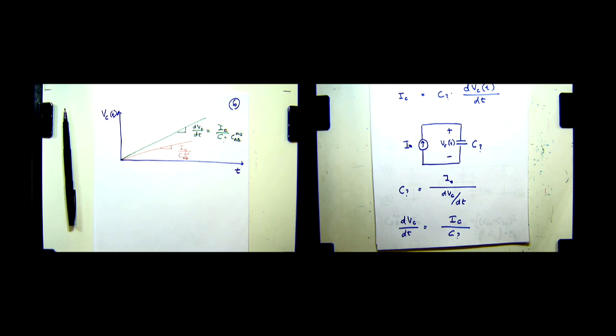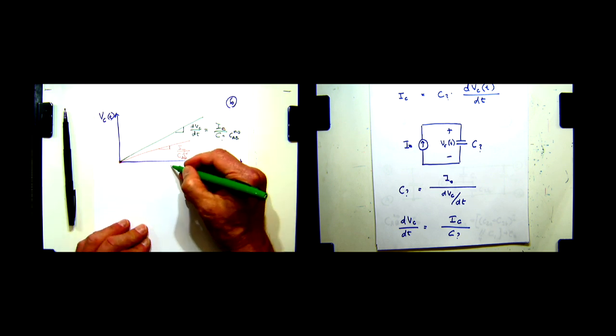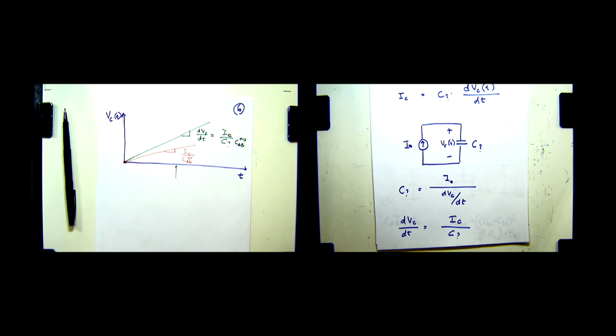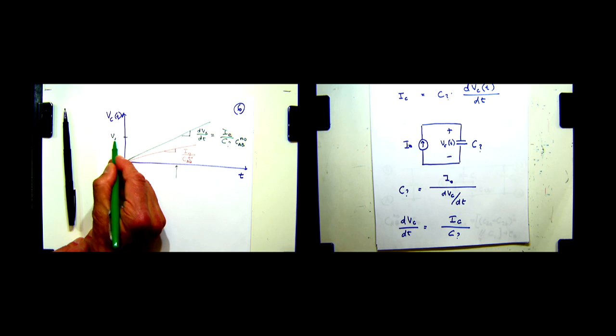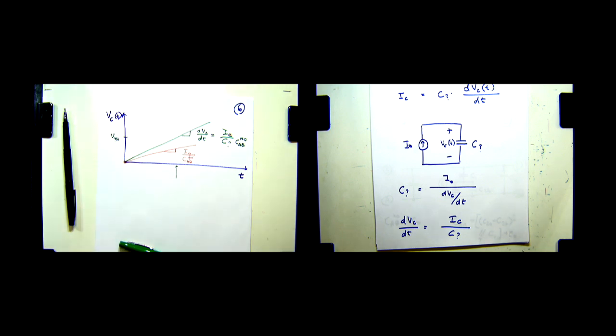Okay, so this kind of is useful. We have to make sure that we always start in the same place, so make sure that the voltage across the capacitor initially is 0. We hook up that current source, and then we measure the voltage. Now, we have to, of course, measure it always at the same time, right? Because the voltage, even the red curve, if let's say your threshold was this much, to detect whether a finger is present or not.